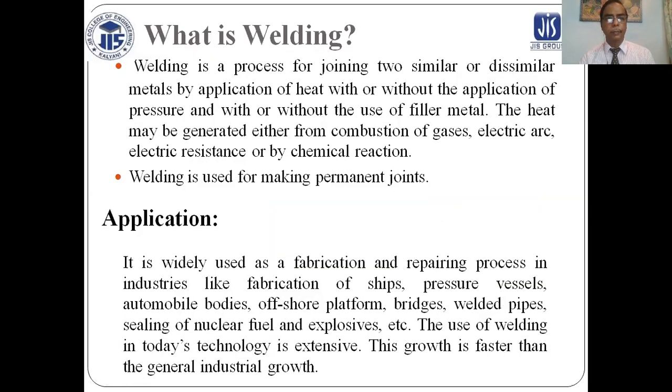So, what is welding? Welding is a process of joining two similar or dissimilar metals by application of heat, with or without the application of pressure, and with or without the use of filler metal. The heat may be generated either from combustion of gases, electric arc, electric resistance, or by chemical reactions. Welding is used for making permanent joints.